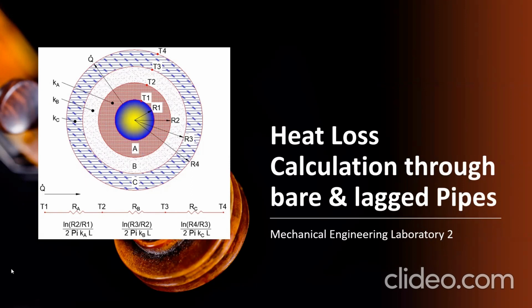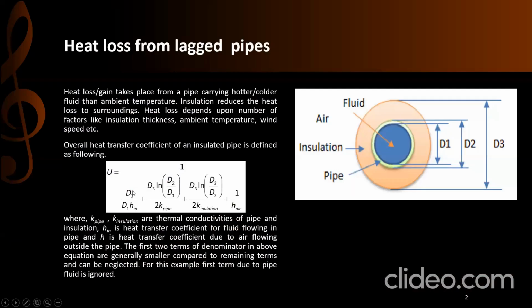Let's discuss that. So you have heat transfer, right? Heat loss from lagged pipe. A lagged pipe means it is insulated. Heat loss or gain takes place from a pipe carrying hotter or colder fluid than ambient temperature. If ambient is less than the surface temperature of the pipe, that is heat loss.